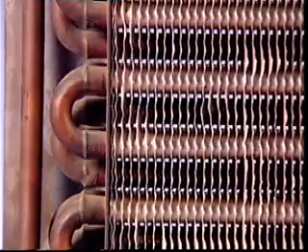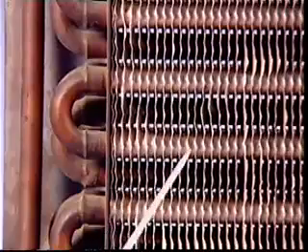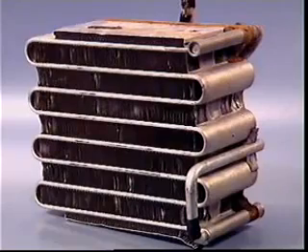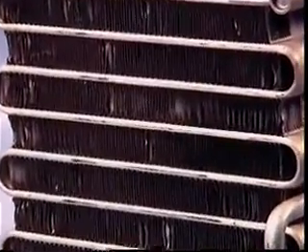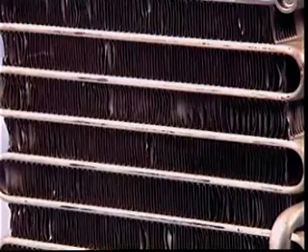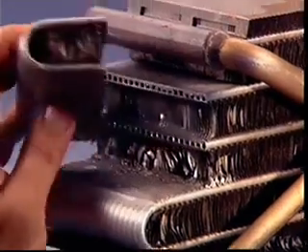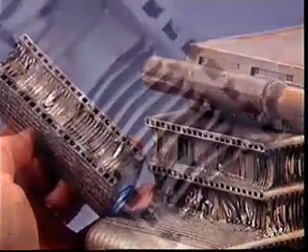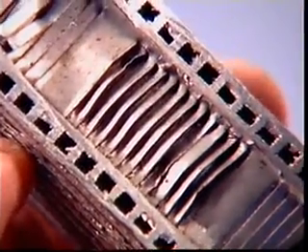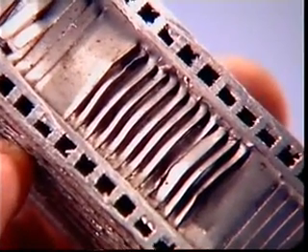The condenser is usually made as a continuous coil of thin tube meshed with a compact series of fins surrounding it. The fins increase the surface area available to maximize the amount of heat transferred from the refrigerant to the outside air. The evaporator is mounted in the passenger compartment and is positioned so that air from the cabin interior can be passed across its external surface. It is normally constructed of aluminium tube with fins attached to increase the surface area. This maximizes the rate of heat removal from the air.